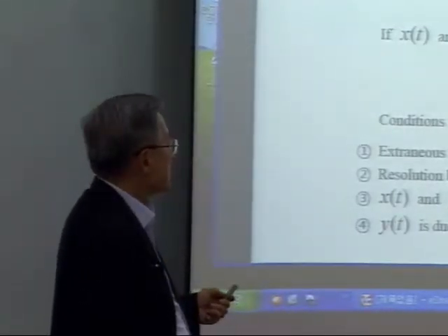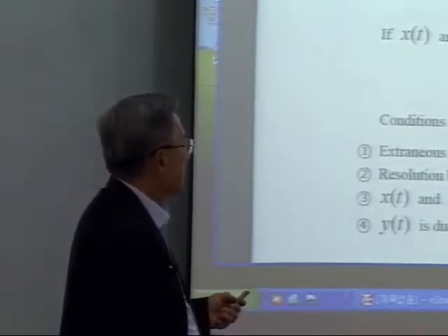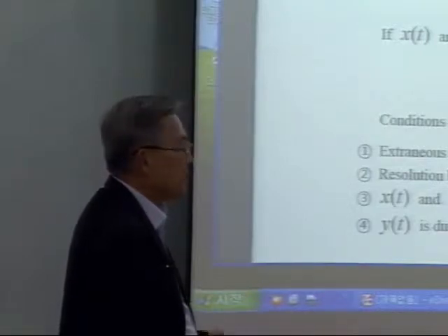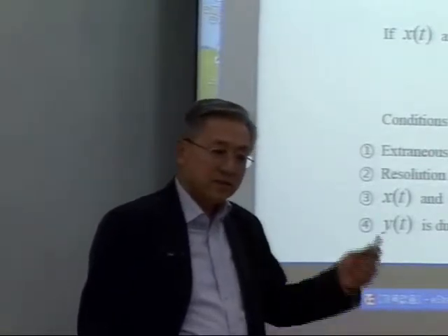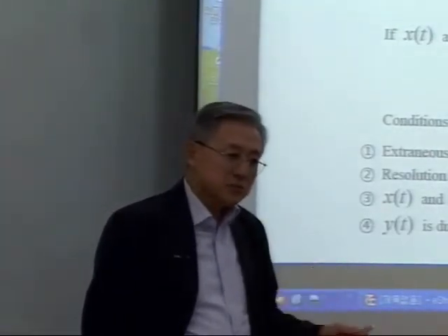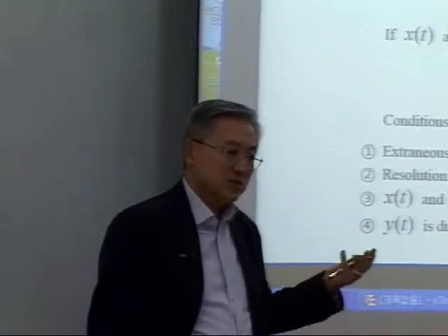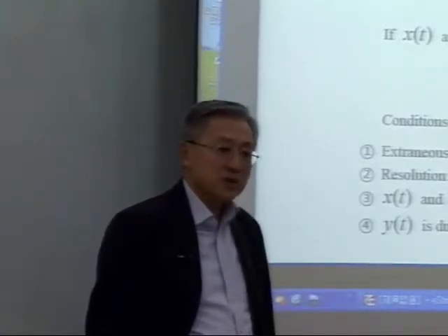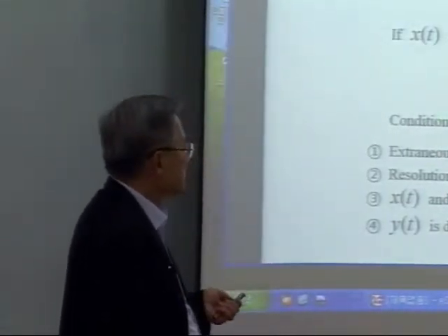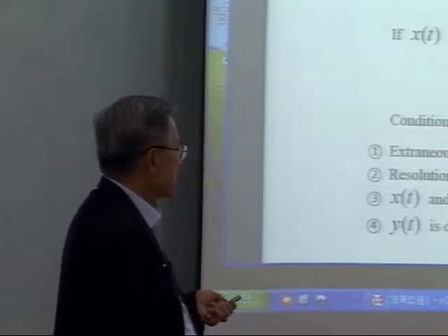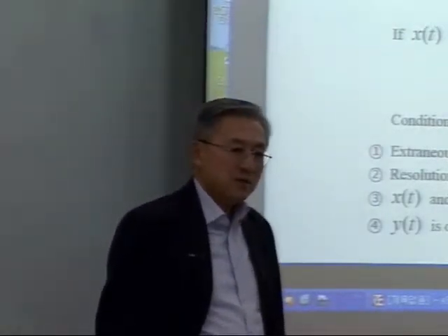Which means this value in the numerator, Gxy absolute square, is equal to 0. So gamma xy square is equal to 0 if y is not produced by x. There is no relation between x and y, which means that Gxy has to be equal to 0. Okay? Under usual conditions, gamma xy square is between 0 and 1.